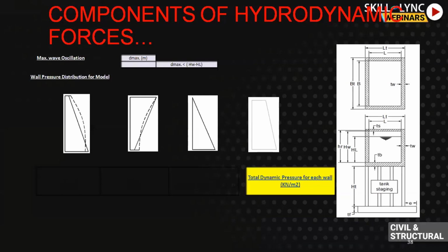In the next picture, in the middle, you will see a diagram showing the pressure distribution is maximum on the top. This is where the convective components come. If you put water in your jug and try to move it, you will see sloshing on the top. This is the sloshing component. Other than the component of water which will try to move with the wall, maximum pressure will be on the top. When we design an overhead tank, we add all these inertial forces due to the wall and tank, the convective forces due to this, and the lateral distribution of water.